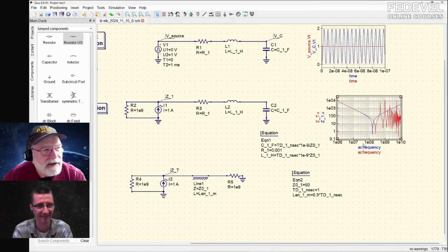But this model says, uh-oh, that impedance oscillates between high and low, open and short, open and short, open and short. So this is only an approximation. That's what you have to watch. At low frequency, meaning when it's electrically short, it's going to look like a capacitor if the end is open, or like an inductor if the end is short, which is fine.